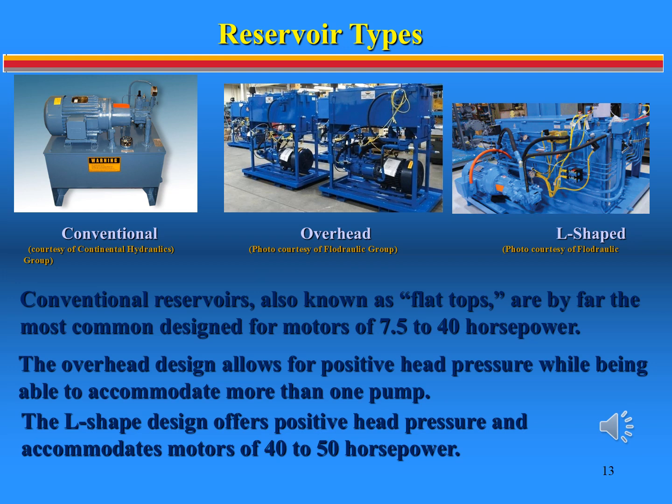The reservoir style you choose will be based on price and available space. You should choose the largest reservoir money and space will allow, and if possible, the tank should permit flooded suction. Flooded suction occurs when the pump inlet port is below the oil level, either inside or outside the reservoir. L-shaped, T-shaped, and elevated reservoirs provide the best combination of attributes, but are large and costly.